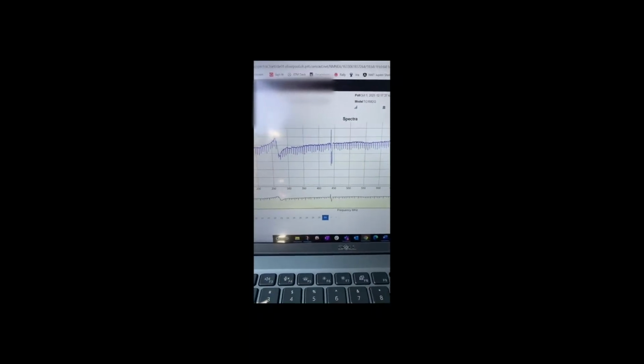Okay, so what we're chasing this time is a pretty gnarly resonant peak. When we look at this device in single device mode, we've got this super gnarly resonant peak here, about 261 megahertz. Looking at the history of this guy, it looks like it's been around for a while, going back at least 4 or 5 days. Before about the 26th, it was pretty flat, and around the 26th, it showed up, and it's been here ever since.